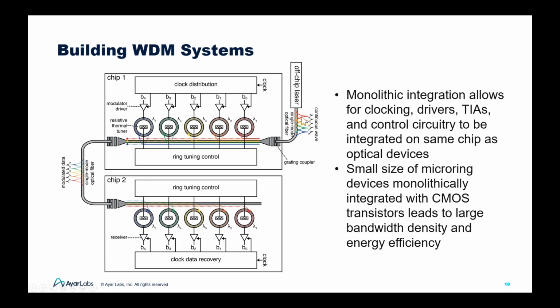In this presentation, we do have an off-chip laser here. For example, right now we picked 5 lambda. 5 lambda is coming here. It's again one single laser cable with the 5 different lambdas on it. And each of these modulators is going to modulate a specific lambda, lambda 1 to lambda 5, and then transmit it over, again, a single fiber.